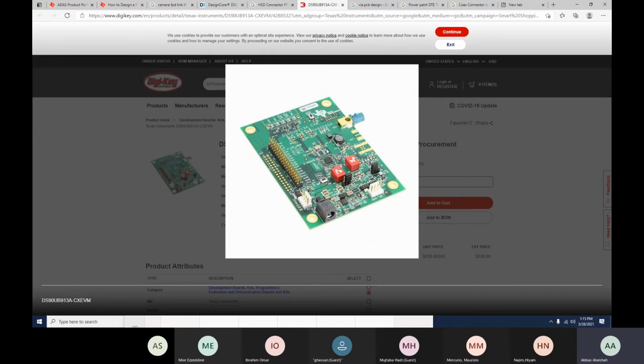You've taken this out. So mechanically, we want to access these switches, this connection, the power, but the rest of them, should you make a housing that leaves this part open? Probably not. Where we need access, we'll leave it open, but the housing should be designed such that it does not allow the user to make a mistake and take out this whole board because they had ESD and they touched this micro.